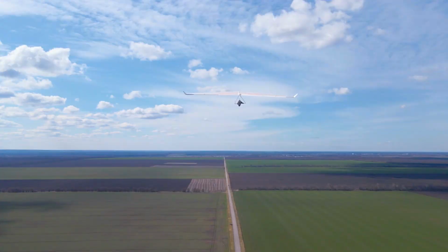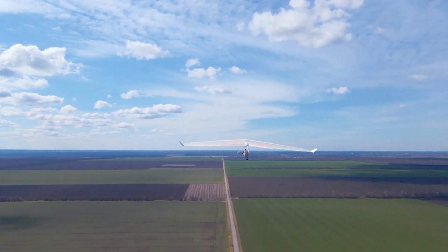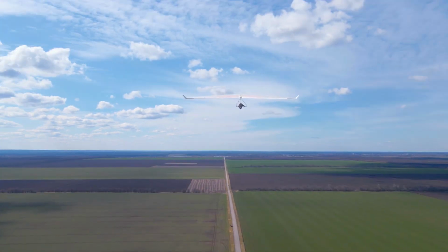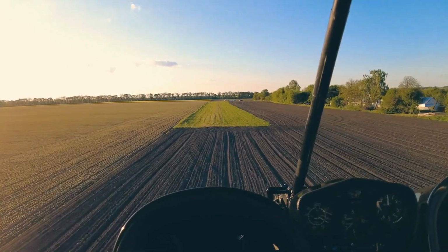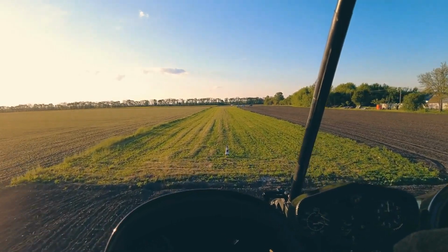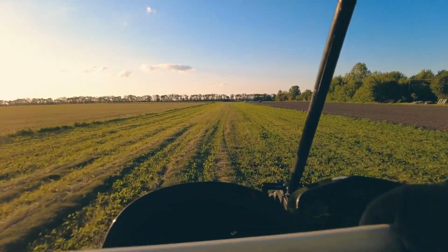Drag is the resistance encountered during forward motion through the air and aligns with the relative wind. There are two primary forms of aerodynamic drag: induced drag, resulting from the wing generating lift, and parasite drag, originating from the friction of air over the aircraft's various components. Understanding wingtip vortices is crucial for flight safety, as they are present in all winged aircraft, and their intensity increases with the size and weight of the aircraft.